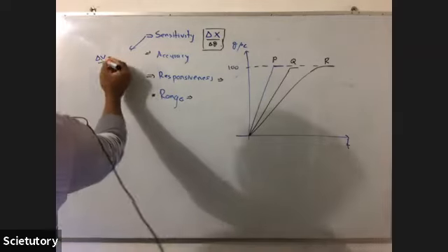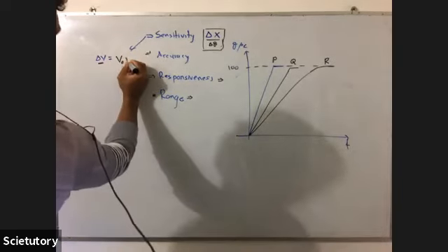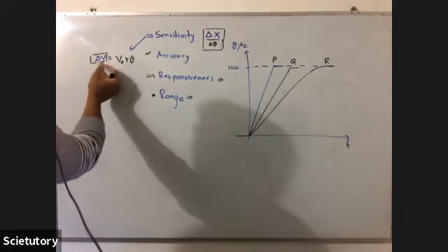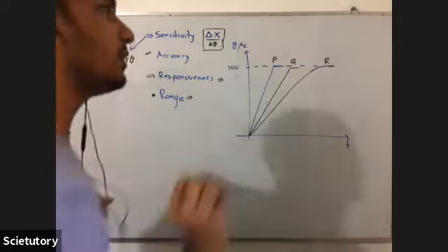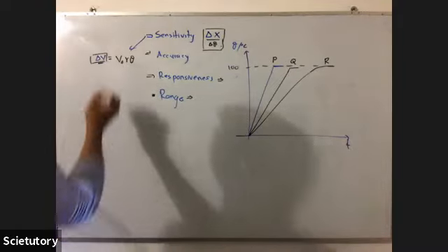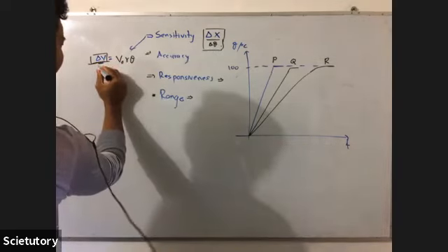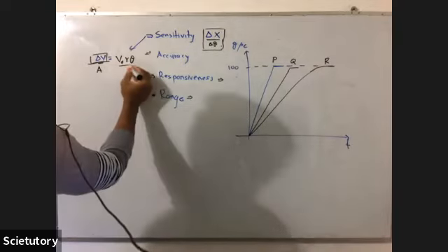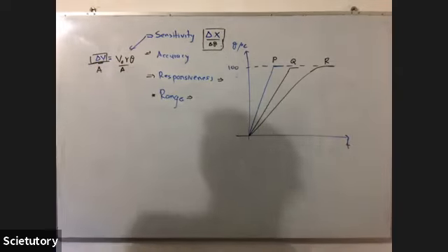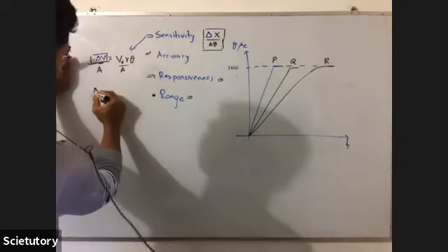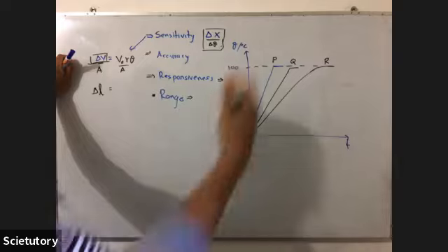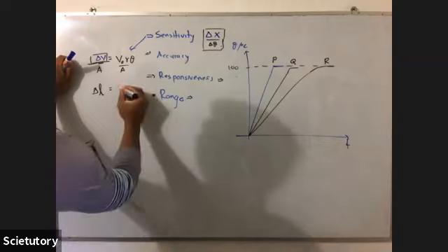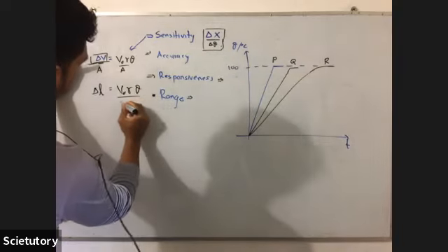Okay, I will explain. This delta V is equal to V naught gamma theta, the expansion of volume. This is a volume increase. So this increased volume is pushed into the capillary tube. So if you divide the volume change by cross-sectional area, both sides, you will get the change of length. What you observe is length, not the volume. In the capillary tube, you are observing the length. So V naught gamma theta over pi r square.